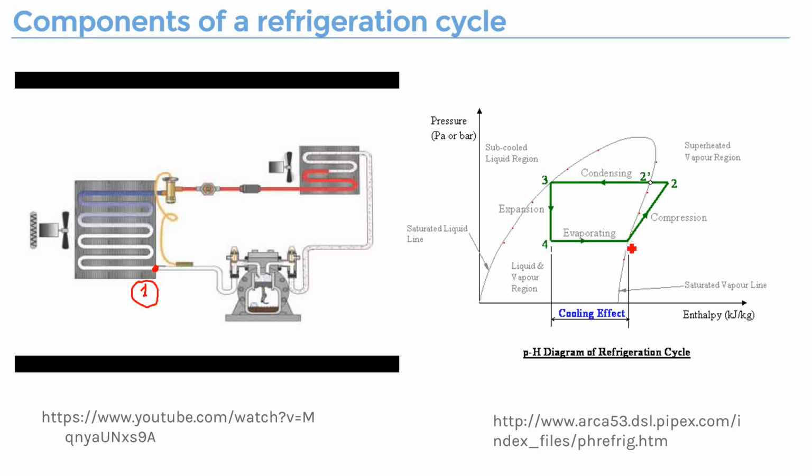Okay. So normally we call this part coming out of the evaporator point 1. So that's on this pH diagram. On this right-hand side, that's saturated vapor. And when it passes through the compressor, it's being compressed. So when it comes out, anyway, that's point 2. So from point 1 to point 2, if you draw a line here, you can see it changed from pressure 1 to pressure 2. So that's what happened in this compressor.